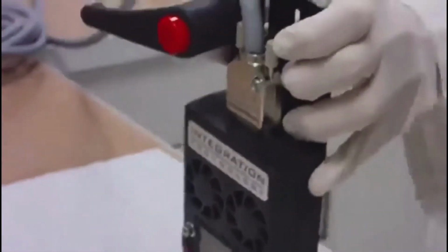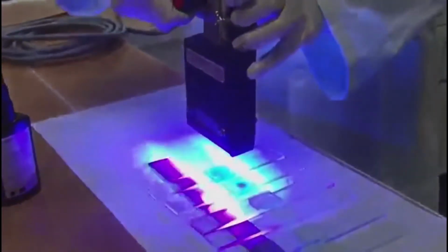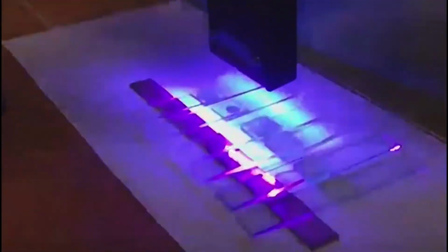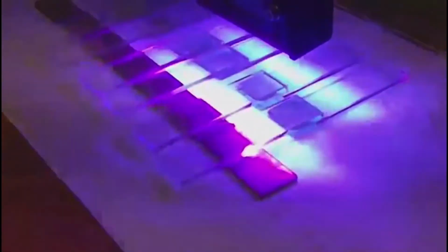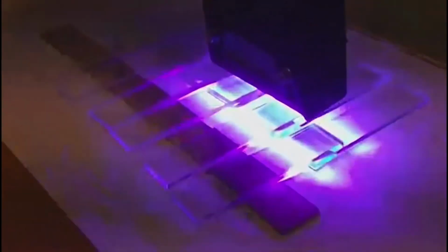The second adherent is being placed in the lap joint configuration. So no edge preparation has been done here, directly application of adhesive and then the placing of the second adherent, and then this is the application of heat, which will help in the curing process of the polymer which has been used for making this joint, or has been used as an adhesive.